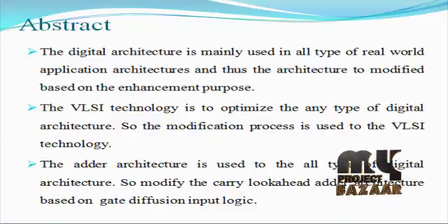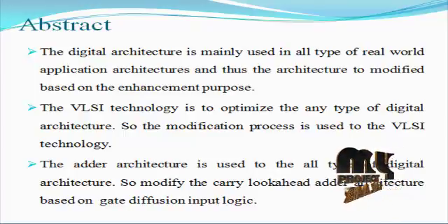CMOS multipliers occupy substantial area and power in digital circuits. To further optimize power and area, it is required to reduce the number of devices in the design of multipliers. This can be implemented using a revised CMOS logic, the GDI technique. Circuits designed in GDI are based on the GDI basic cell, which allows us to apply more than one input, in GDI based architectures.